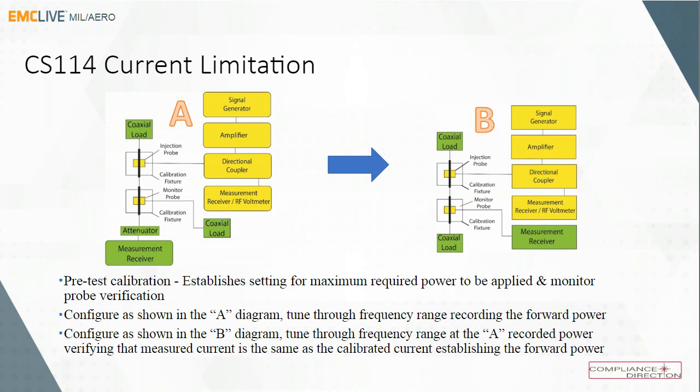Now, quite often if you use one probe for CS114 and a different probe for measuring CS115 where that's not there, we've done no calibrations to the CS115 test. So the idea is it's there, but there's a pitfall if we don't validate the probes that we're using for other things that's no longer getting the periodic calibration or the higher level validation checks. So that's one of the pitfalls that we need to be concerned about.